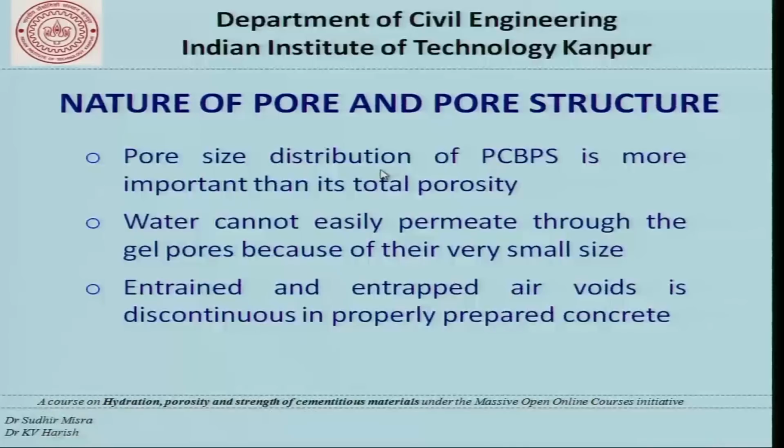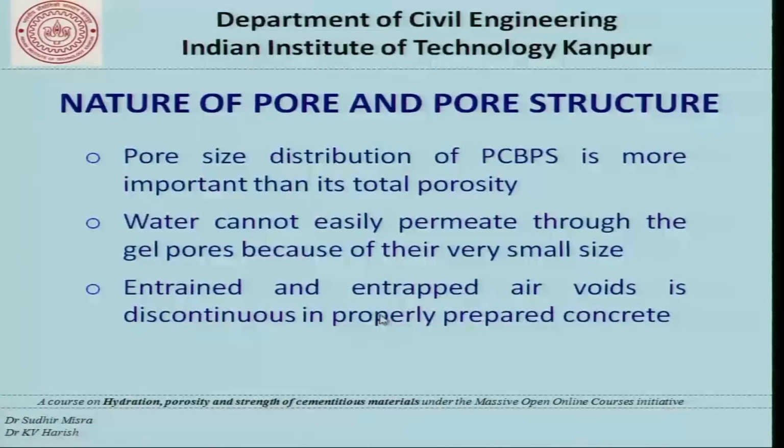Pore size distribution is more important than its total porosity, as already mentioned. Water cannot easily permeate through the gel pores because of their very small size. Remember that water to some extent can permeate through capillary pores but not through gel pores, because gel pores are smaller in size.